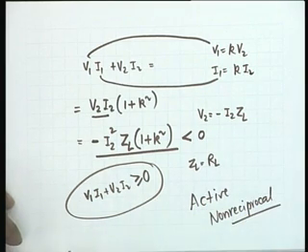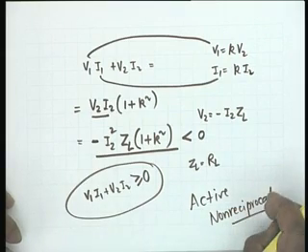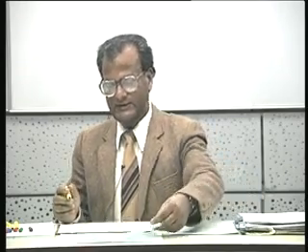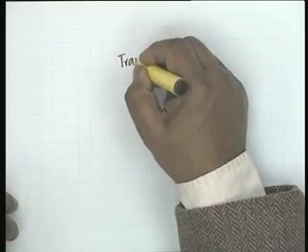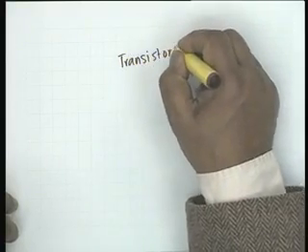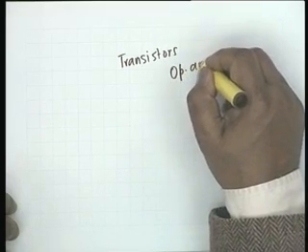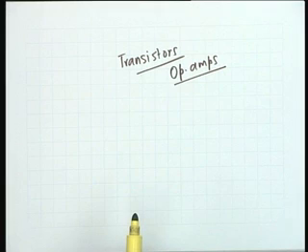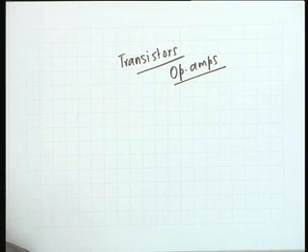And obviously, if it is non-reciprocal, it cannot be made out of RLC elements, positive R, positive L, positive C. We must have non-reciprocal, non-unilateral elements like diodes or transistors, or a combination of transistors to make an op amp. In fact, an NIC can be made with transistors and or op amps, and simple circuits can be built to demonstrate the action of NIC. If you are interested, we shall look at some circuits at a later stage.